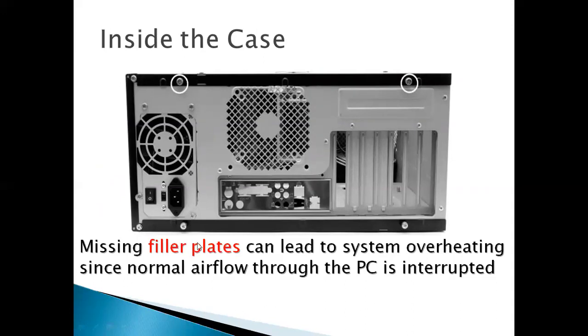Next, missing filler plates can lead to system overheating since normal airflow through the PC is interrupted. So filler plates should always be there, because of them there will be air circulation inside the PC. If there are no filler plates, then the system will overheat because there will be no air circulation and no ventilation.